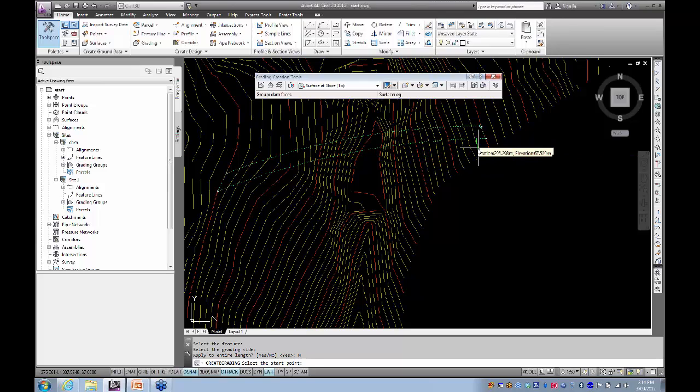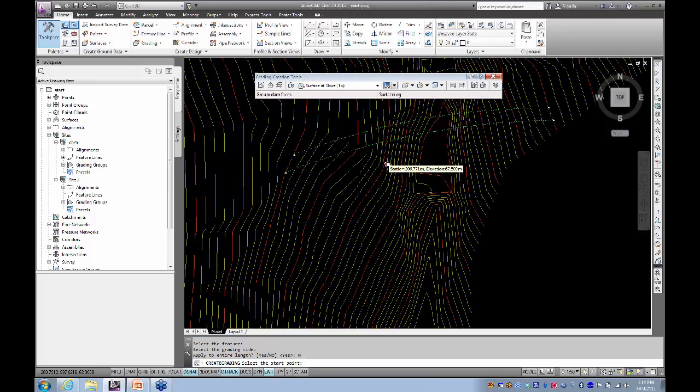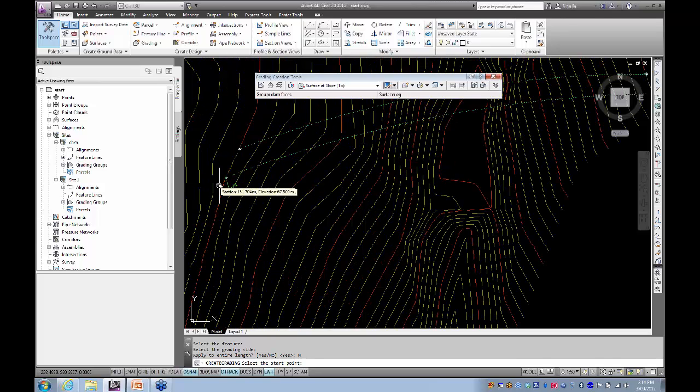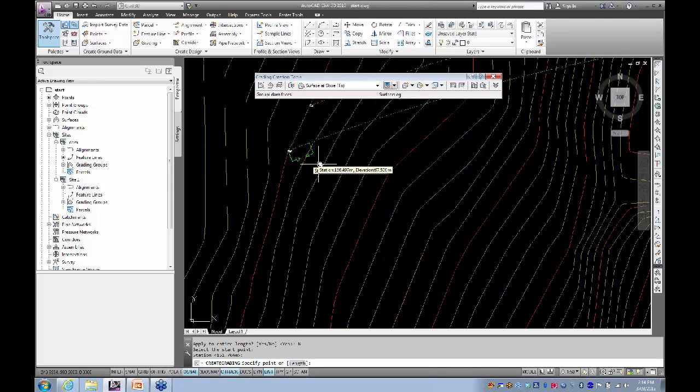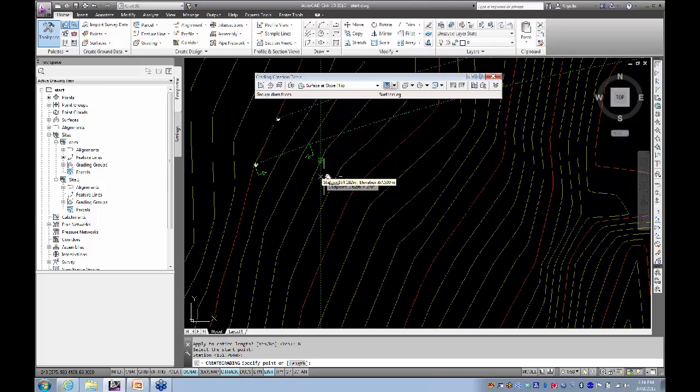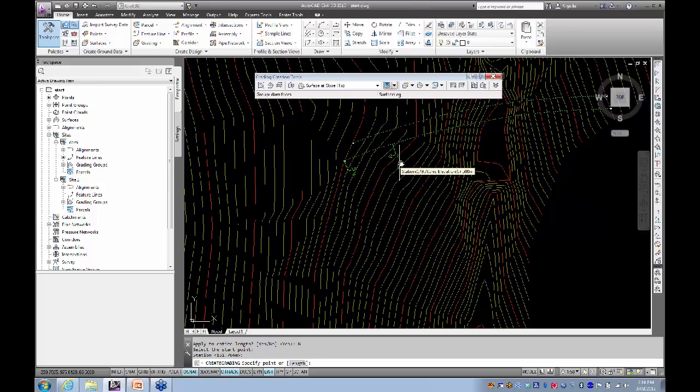When you do that, you get a little arrow that runs around the feature line that you've created, so you can say where it starts, where it finishes. I'm going to click there to say it's going to start at that particular point, and then it asks to confirm the station, so I'm going to hit enter, and then you can see it makes two little arrows that specify where it's going to make this grading from and to. So I'm going to come over to here somewhere.